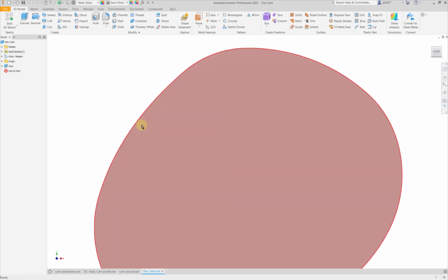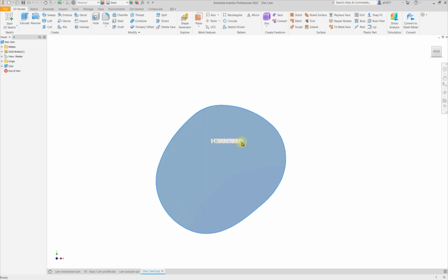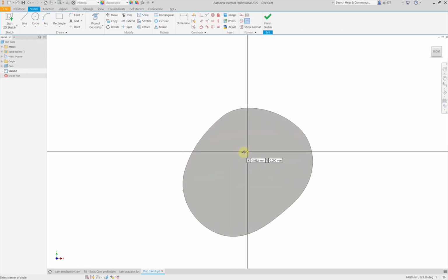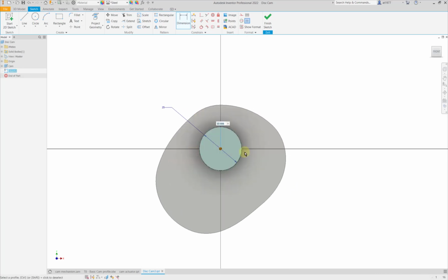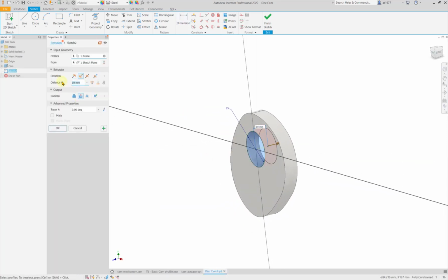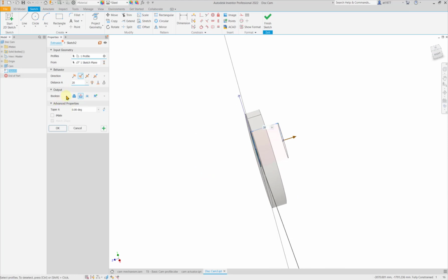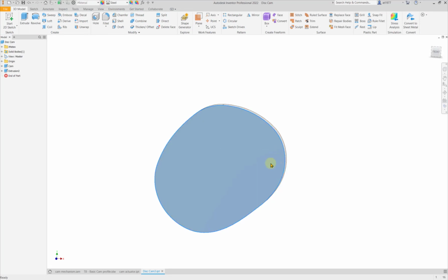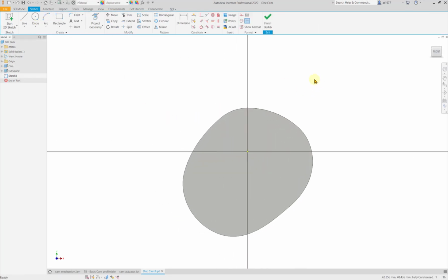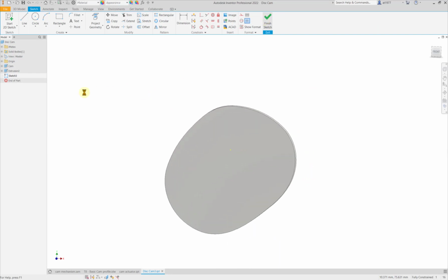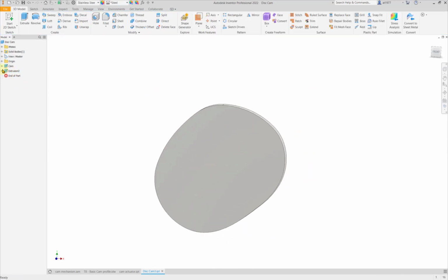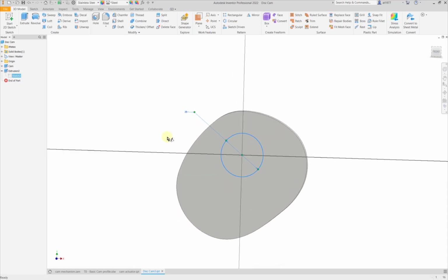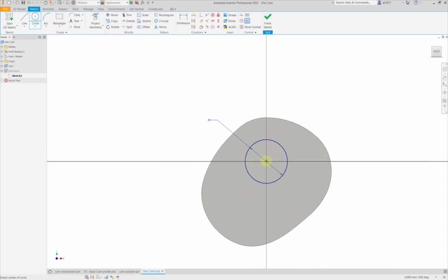So I can open up, create sketch. The diameter is 25 mm. Extrude, the other direction 20. Make sure it's join and press OK. Why is this in this direction? I've got to mention, you can actually check to see if it's correct or not. Let me delete away the sketch tree. Edit the sketch. So I create a base circle.